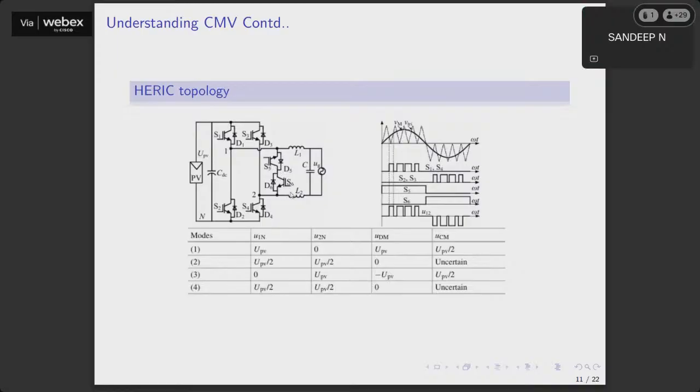So that is going to ultimately short circuit this path. Then if you look at the rest of the switches, your S1, S4, and S2, S3, they are open. So you are going to open all these 4 switches and switch on the bidirectional switch. That is going to ultimately cause 0 and the PV is disconnected from the path.